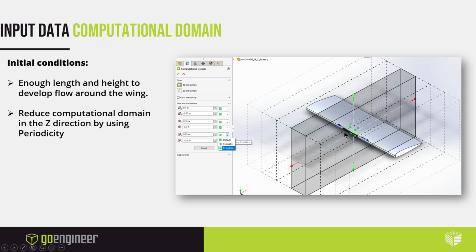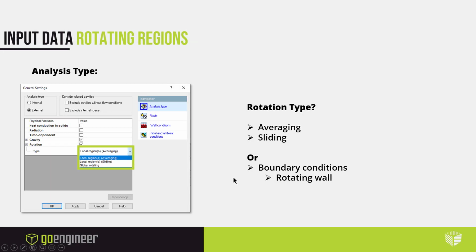So that'll play an effect. That's why you see the shallow blades I designed. They only span 100 millimeters because periodicity is just basically going to do a periodic computational domain out for the remainder of the wing on both sides. Okay, so I have a rotating region.